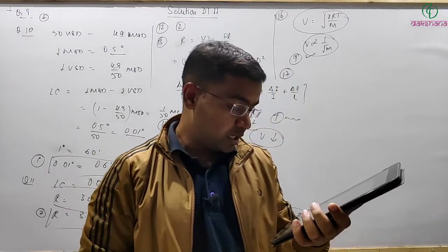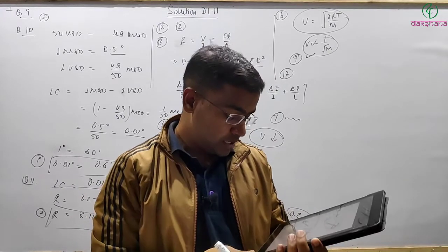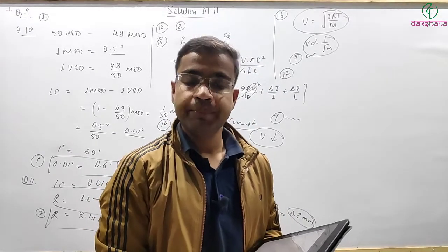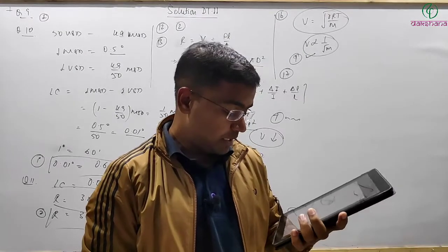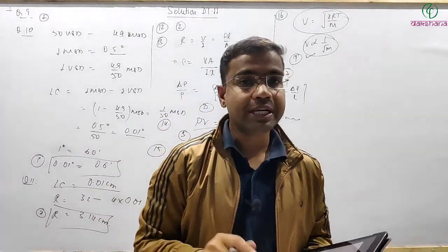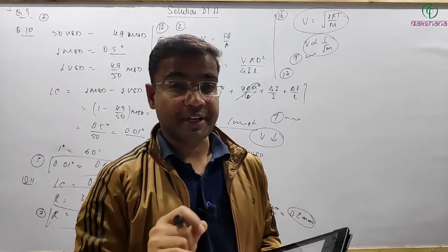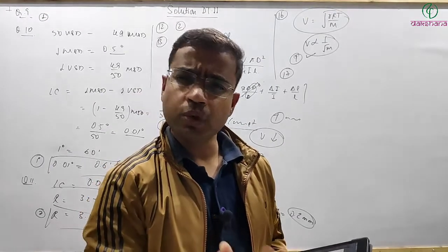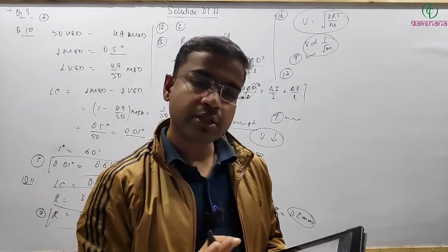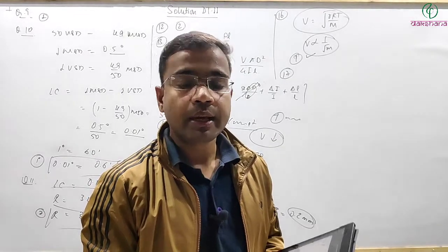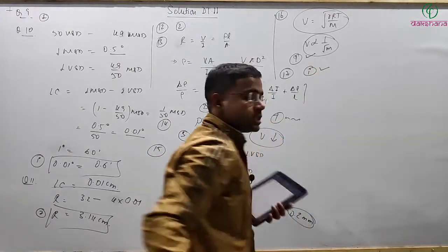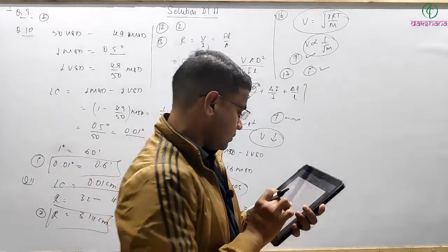Delta U in a non-cyclic process of an ideal gas. Okay, so delta U equal to 0 in a non-cyclic process, and in isothermal it is also 0. But here it was asked whether the process may be isothermal, must be isothermal, may be adiabatic. Look, delta U depends on the initial and final states. So even if the process is a different one, but the temperature of the initial and final states is the same, then also delta U can be 0. So in isothermal it will be, but it's not a must actually, in other processes also. So that's why the right answer will be the first one. It may be isothermal. Okay, second question.